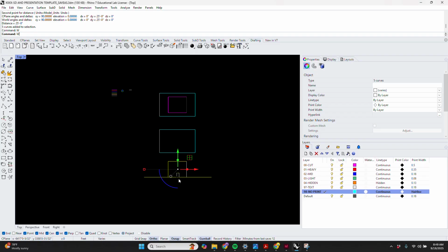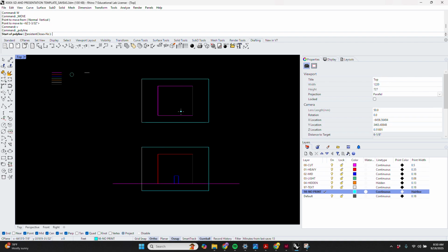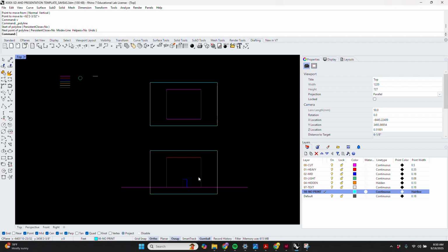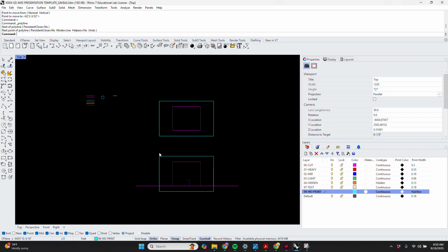And then I'm going to bring my geometry up and centered to align with that. So let's see, middle, so it's centered in this line, and now I'm going to center that on the paper. Great. So these now also, just for your own sake, are aligned here, which is not exactly required, but that's the kind of modeling, drawing hygiene I like to have in things. It makes everything easier. Okay, so great. We have this set up in model space.